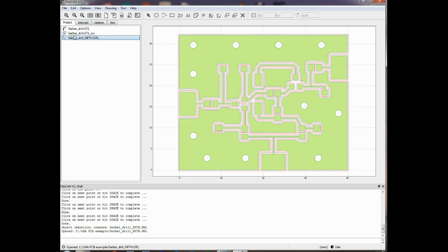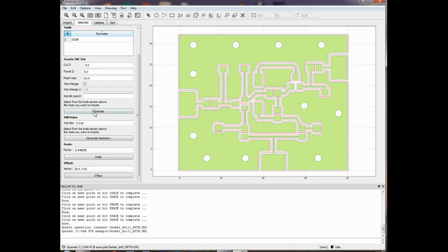you can now generate all the other steps, and then ultimately you end up with 3 G-code files. You end up with a G-code file for doing the actual relief, the PCB itself, what you're trying to achieve, the relief milling. You end up with another G-code file which does the holes, tells the machine where to drill the holes, and then you end up with a third one which is used for doing the board cut outline, for cutting the outline.